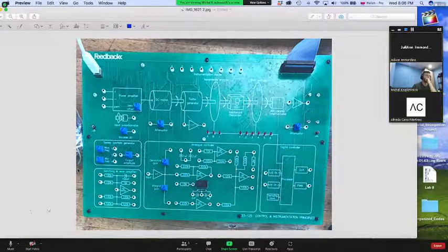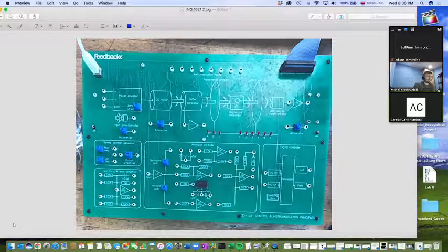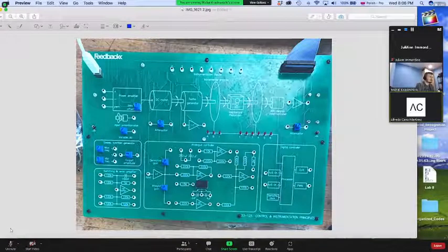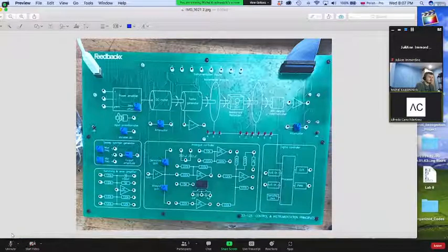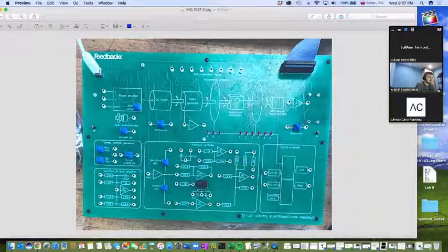Yeah, that makes sense. So this goes back also to Michael's question as to why the KP doesn't really stand for position, because if the feedback is a speed, right? If the desired signal that I want to reach is a desired speed, I can feed back the speed, and the only thing I need to worry about is the error signal. So multiply the error times some gain, and this will give you a proportional signal, right? So this KP really stands for proportional as opposed to the position gain. You see what I'm saying, Michael?